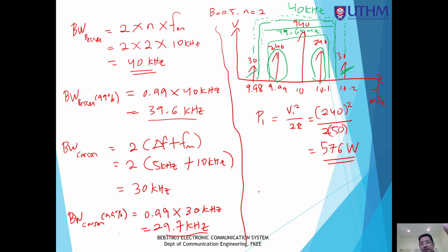Previously we had the modulator over here, and then another filter, a band pass filter. The modulator produced the FM signal, where you need to find the total power using the Bessel equations. This is 100% of the total power.